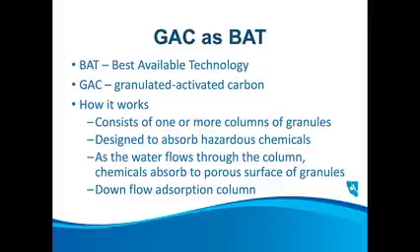So let's talk a little bit about GAC as a best available technology. So BAT means best available technology. It's a regulatory term. When they issued this MCL, they specified that GAC was the technology for treatment for trichloropropane.